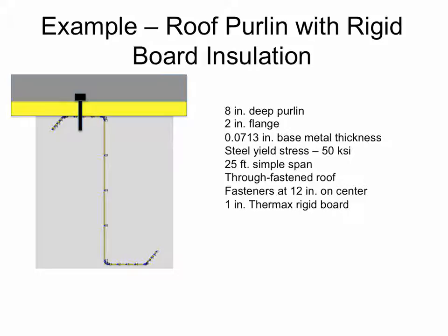And then we have a 25-foot unbraced, or 25-foot span. So will the lateral torsional buckling be affected by the insulation? It sure will. So you are probably not fully braced anymore, and so how would you take that into account? What was your name? Bob.